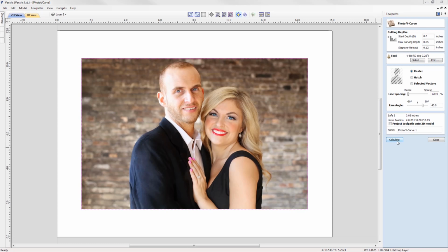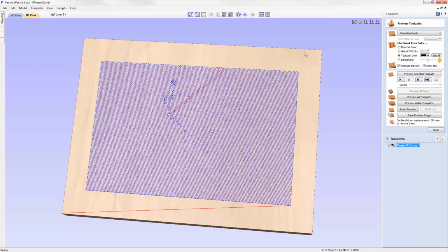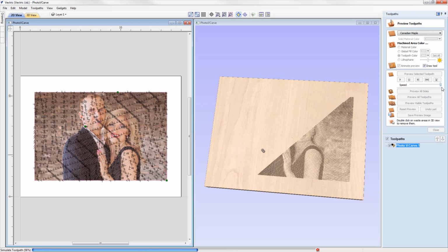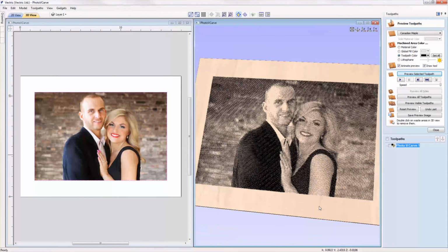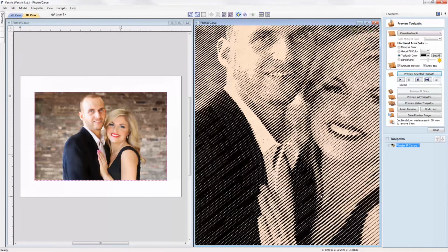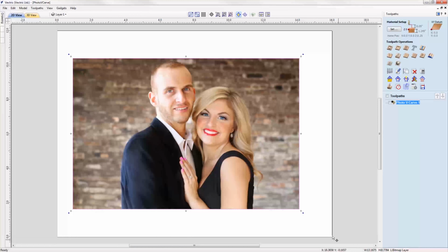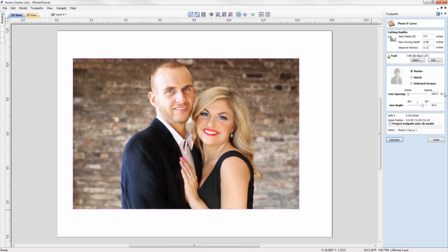We've introduced a new toolpath to the software, the PhotoVCarve toolpath. This toolpath strategy enables you to use a V-bit tool to etch a picture into the surface of your material. The software takes your image and creates a series of lines at different depths to produce the desired image. Simply import your image and select it with the PhotoVCarve tool. Specify your cut depths and choose a tool to use, then select a strategy.